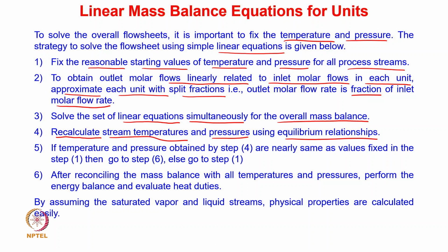these obtained temperature and pressures by using equilibrium relations are matching with the temperature and the pressures which we have assumed initially. If the temperature and pressure which we have assumed initially are matching with these recalculated temperatures and pressures from the equilibrium relations, in that case we directly go to the step 6, where after the mass balance with all temperatures and pressures, we perform the energy balance and evaluate the heat duties.